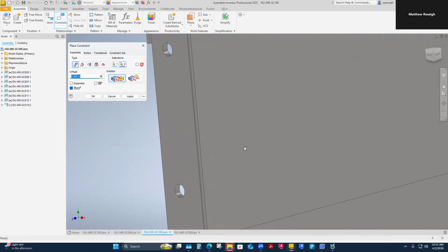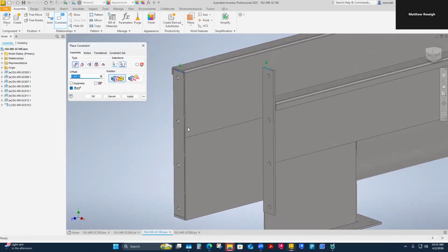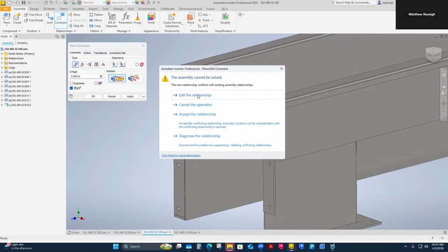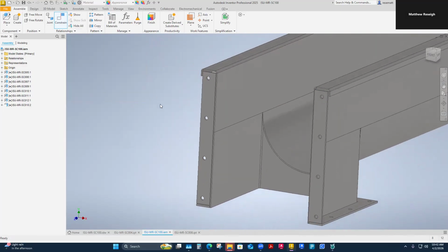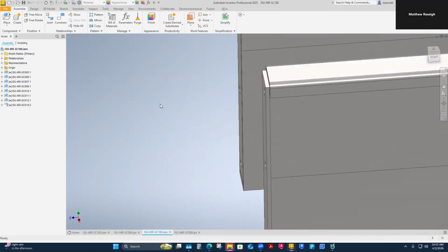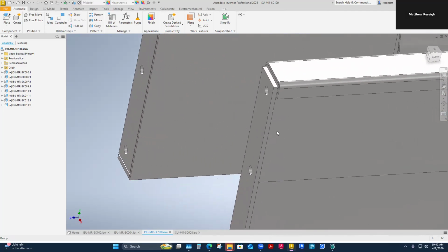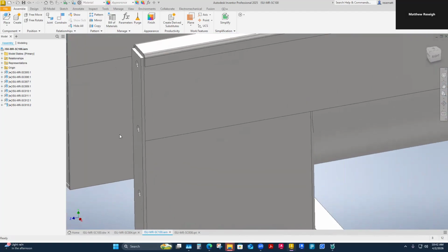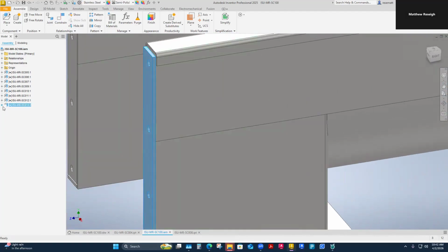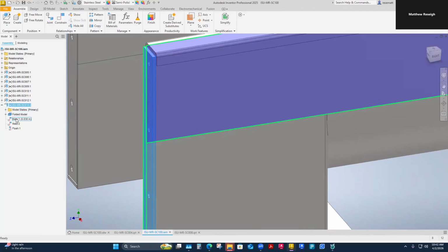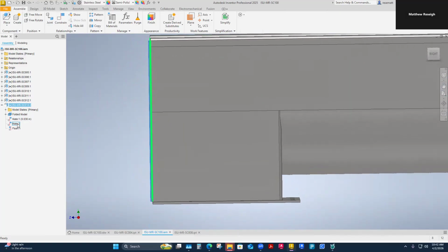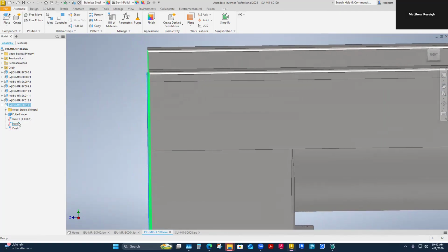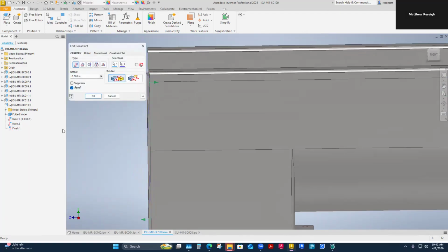So I'm using that nice ground and rooted position. If that one doesn't work, I'm going to choose the other selection. Ah, that was it. And apply that. So now I've got an issue there on that one though. I've got to reverse one of these constraints on this. So I'm going to open up its constraints. That's the 30 thousandths mate. I think I may need to reselect the face that I'm flushing up here. So I'm going to come into this and edit this constraint here.